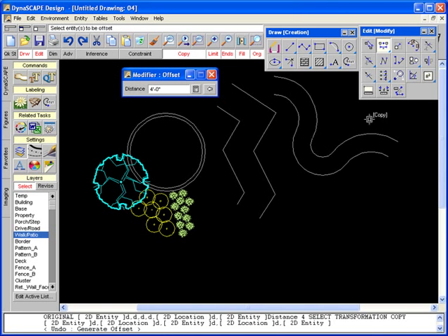There are a couple of rotating tools in the Edit toolbox that we can talk about as well. The rotate objects around a location is the simplest one to use, and it's dependent on both the copy toggle and the constraints. So if my copy toggle is on, that means it'll rotate it but leave the original. If I just want to rotate the object, in most cases that's likely the situation where you want to actually rotate it and remove the original, turn copy off.